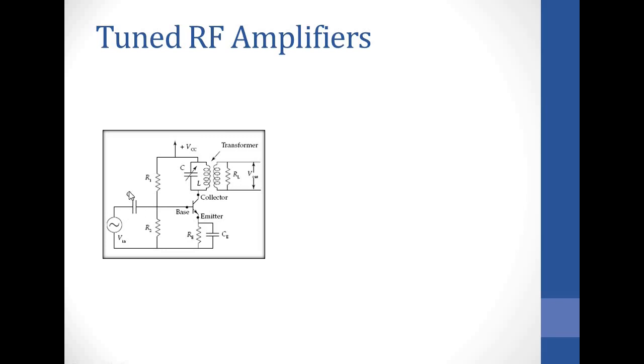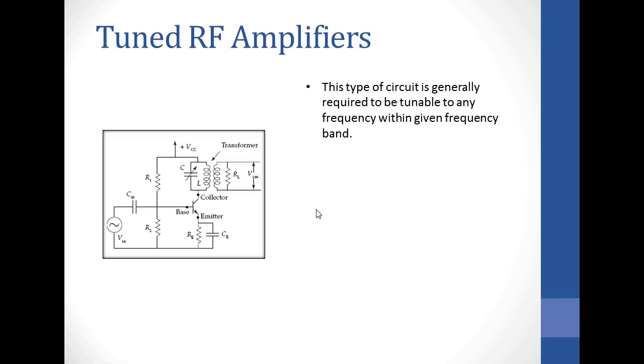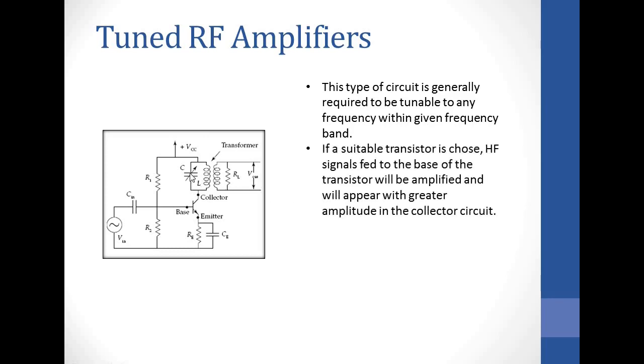And the capacitor is an input coupling capacitor which couples the input signal to the base of the transistor, and the function of the transistor is to amplify your signal. So besides that theory about electronics, as an RF amplifier, this tuned circuit, the LC tank, is the one that makes it a tuned RF amplifier, whereby it selects a certain band of RF frequencies to amplify. It can also be variable, whereby you can vary the frequencies that you want to amplify.